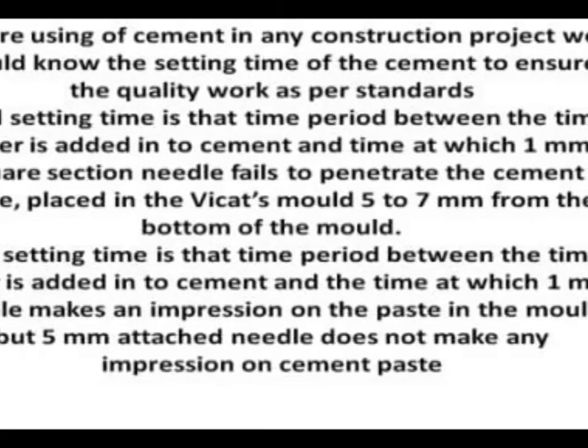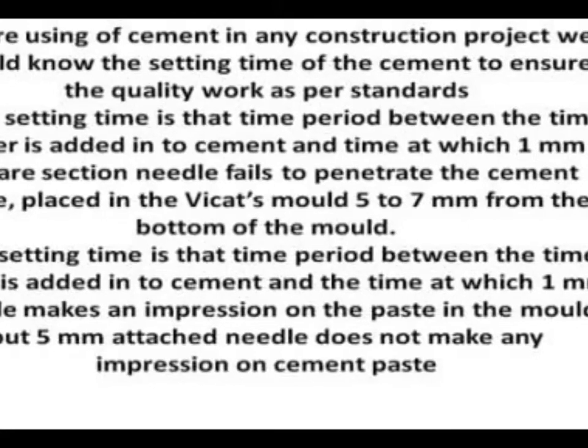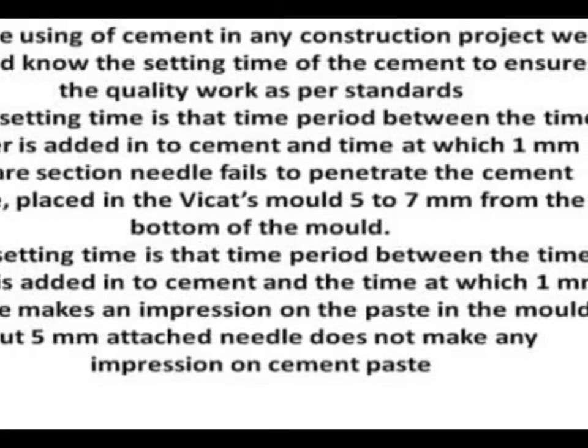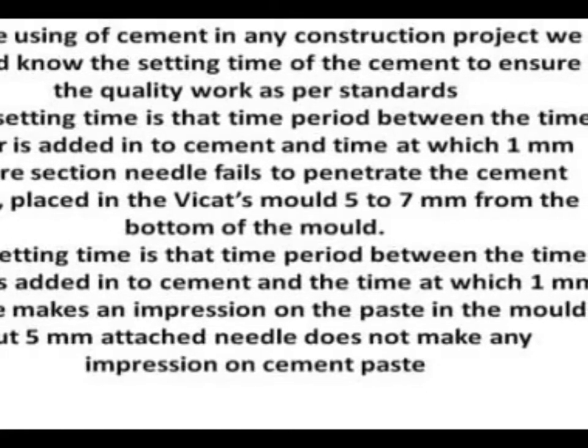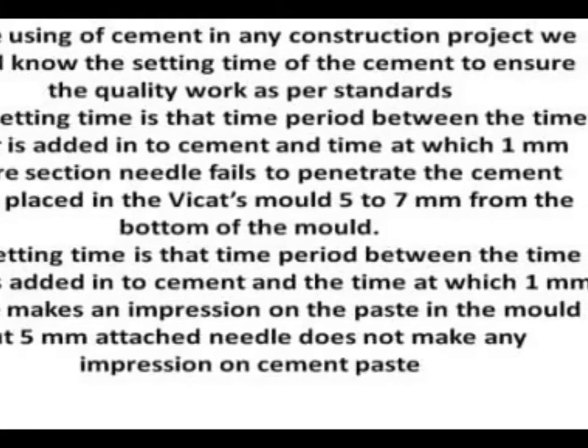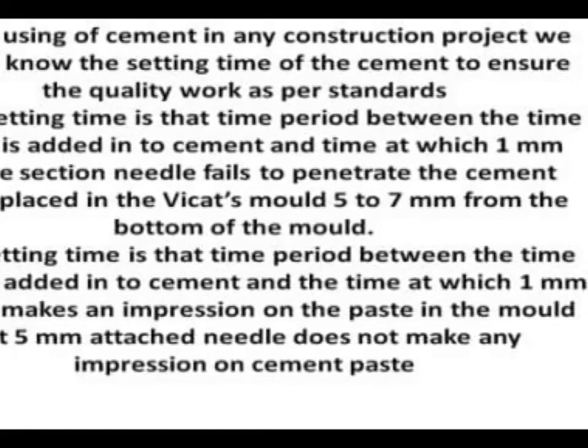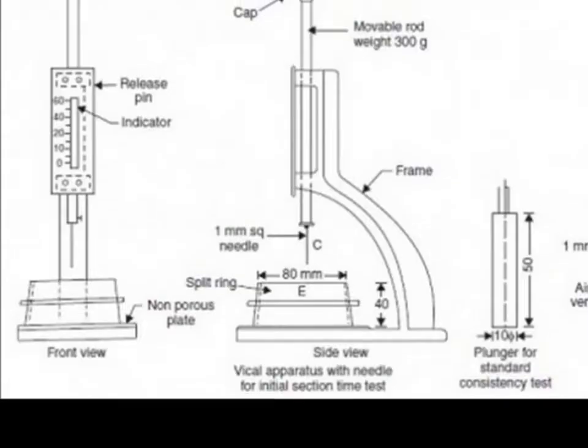Final setting time is the time period between the time water is added to cement and the time at which the 1 mm needle makes an impression on the paste in the mold, but the 5 mm attached needle does not make any impression on the cement paste.